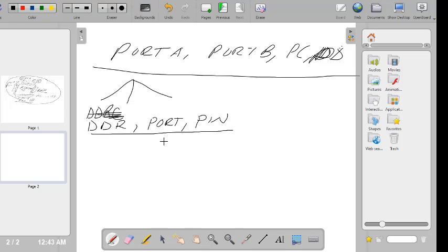So these are the 3 things that you need to appreciate whenever it comes to programming a port of the ATmega32. You need to appreciate that the port has got the data direction register, the port register, and the pin register. Now you have to appreciate the fact that the ports are the eyes of the microcontroller. These are the places where we can input data and output data from. So for us to be able to program, we need to understand these ports in terms of what I've just written right here.